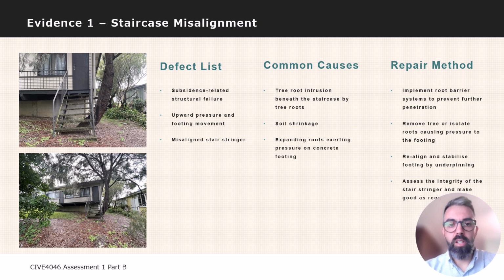During our site visit, our primary concern involves the concrete footing beneath the staircase, which has exhibited structural instability due to tree root intrusion. Root activity has caused differential settlement, structural misalignment, and visible cracking, increasing the risk of collapse. The defect mode included upward pressure from expanding roots, exacerbated by inadequate foundation design, leading to footing displacement and stair-triggered deformation.